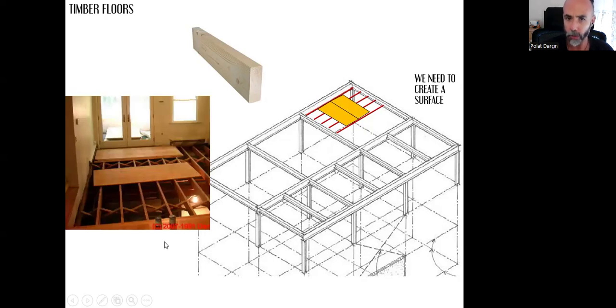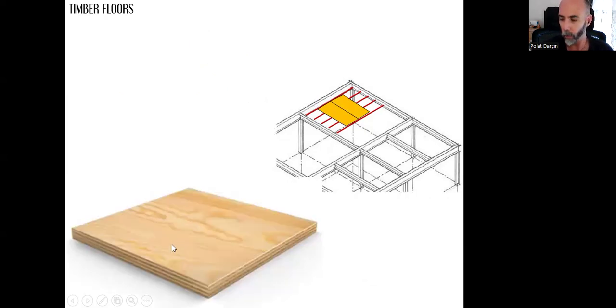So something like this. And for the boards, we can use engineered timber panels. These are thin but large panels, and there are different types. This is called plywood. In Turkish, we call it kontrplak or katmanlı ahşap levha. And as you can see, it's created with very thin, like 1 millimeter or 3 millimeter thick natural wood panels, and they are positioned in opposite directions, just like we examined in the glue laminated timber.